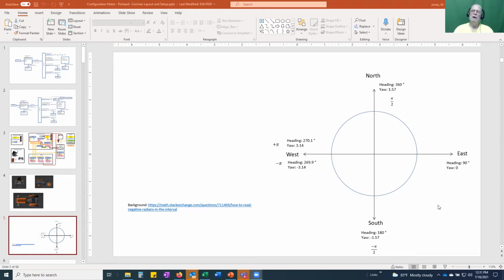So anyway, I was playing with that. I can now extract the heading and the velocity from that velocity message from any of the drivers, and I'll play around with that some more and see what I can do. And then again, it comes back to the fact of which direction of rotation do I want and all that kind of stuff. That's where I'm trying to figure out that magic line, because that GPS odom.py, I don't know if that's correcting for the north-east-down to east-north-up.